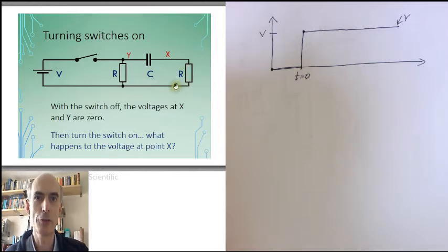And that current would take some of the charge off this plate of the capacitor. That will increase the voltage across the capacitor, and that current will continue to flow through this resistor R until point X has got down to 0, assuming that we've defined the voltage at the bottom of our circuit here as our local reference of 0 volts.